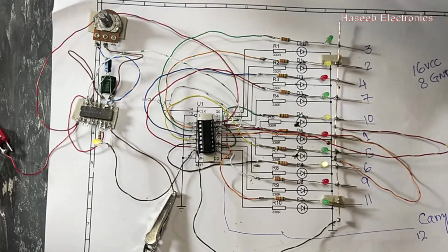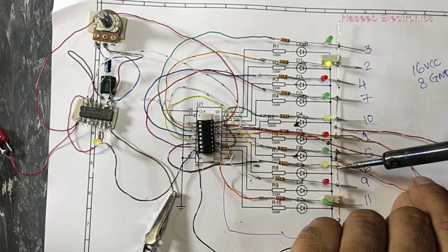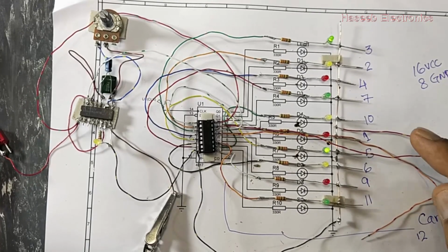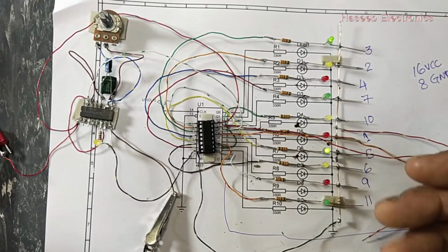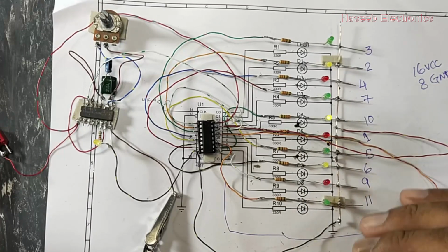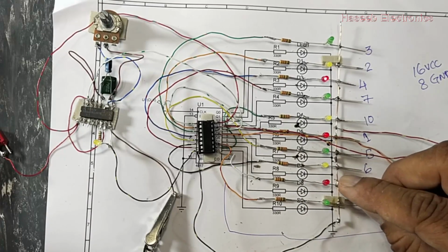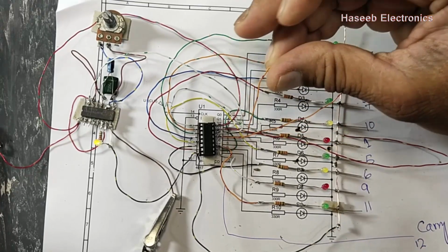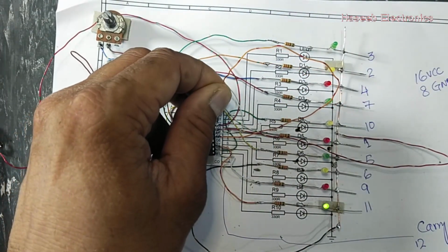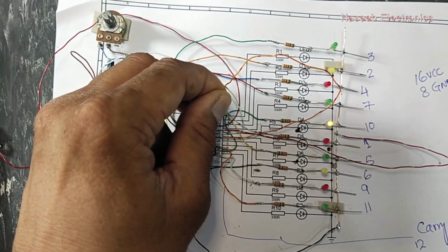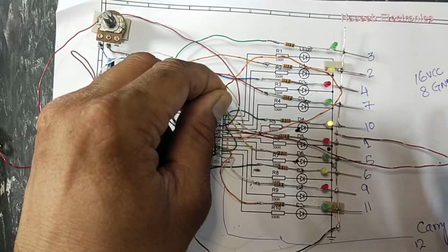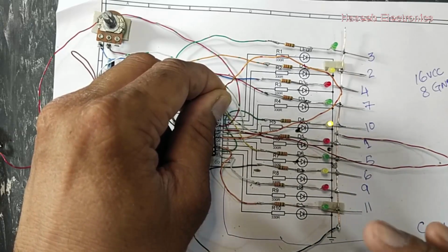Let's stop it. So that is pin number 13. So pin number 13, that is here. If pin number 13 is not connected, it will do some random behavior. If we connect it to ground, it will work normally. And if we connect it to the VCC input, then it will stop. Now it will not work because we disabled its function.